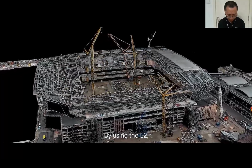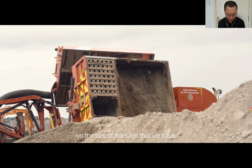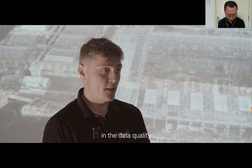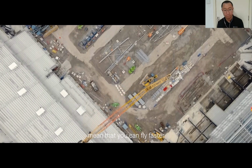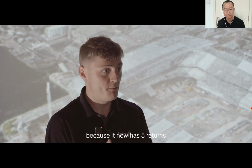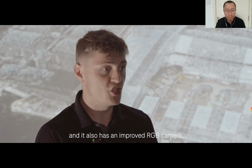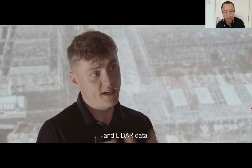By using the L2, we're able to generate data for earthwork movements, including volumetric data. This is invaluable on the size of the sites that we have. There are some clear improvements in the data quality from the L1 to L2. The improvements of the sensor mean that you can fly faster for greater efficiency and collect more accurate data even when flying higher. It has better vegetation penetration because it now has 5 returns instead of 3, and it also has an improved RGB camera, which means that you can have greater efficiency when collecting photogrammetry and LiDAR data.